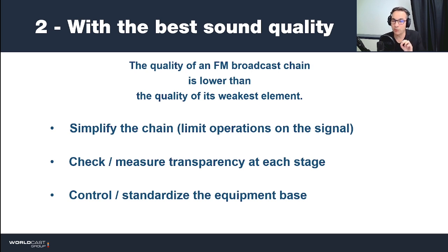We want to limit the operations on the signal. We want to check and measure the transparency at each stage. And we want to control and to standardize the equipment base, because we want the FM station to be received with the same quality over different transmitter sites across the country, for example.